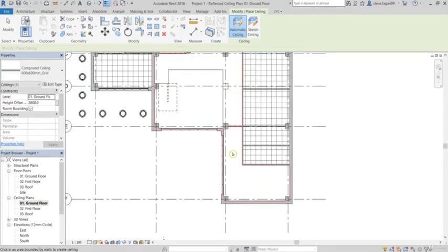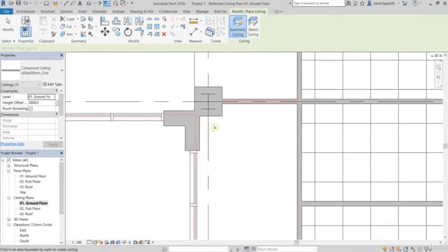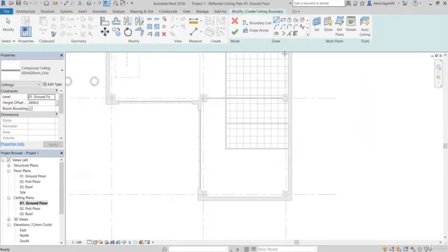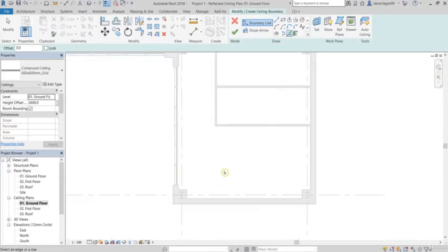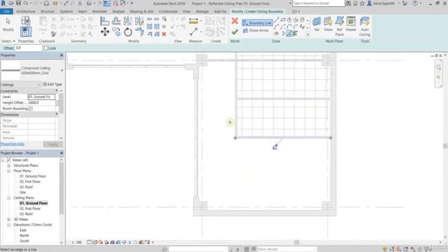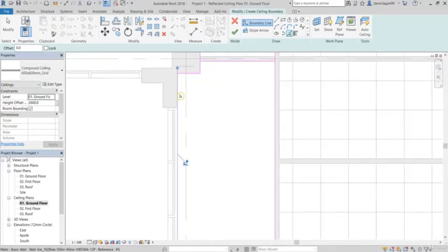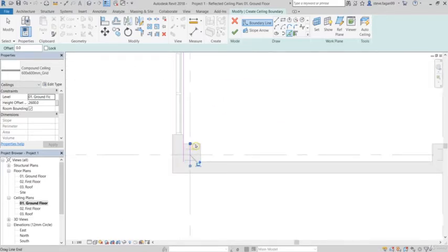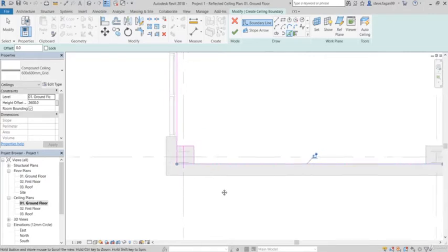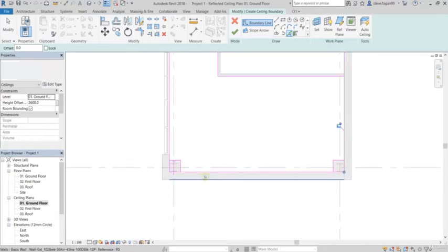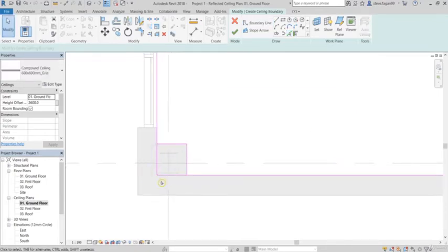Again, for the lower right hand room, you can see it's spilling in past that architectural column. For this one, again, I'll use the sketch ceiling, use the Pick Lines and run along the inside face of the room. And then trim to finish.